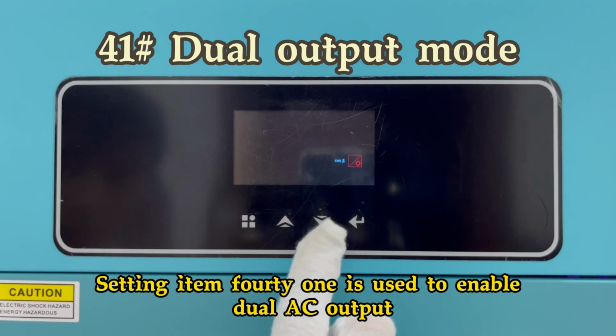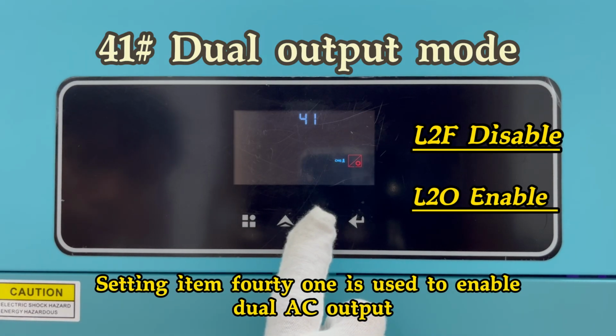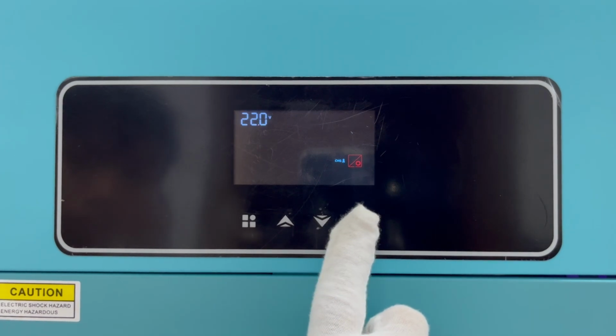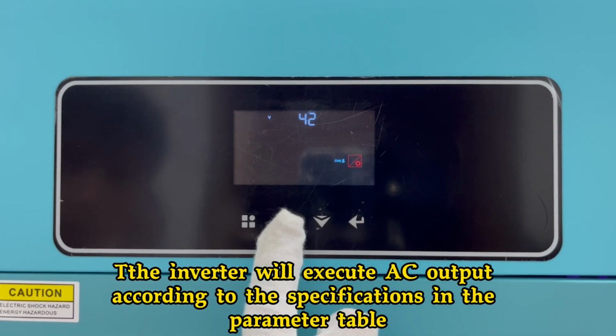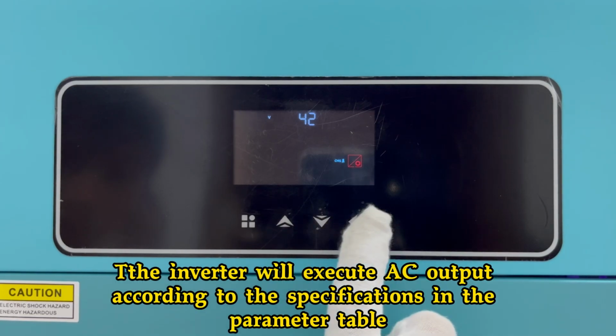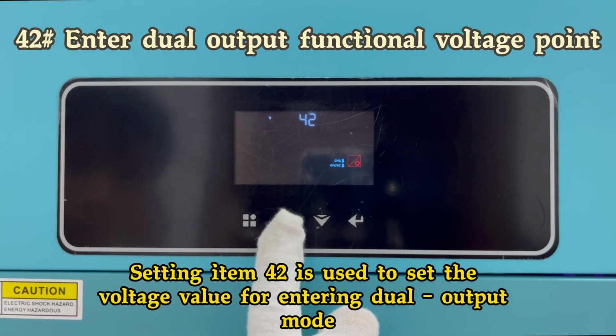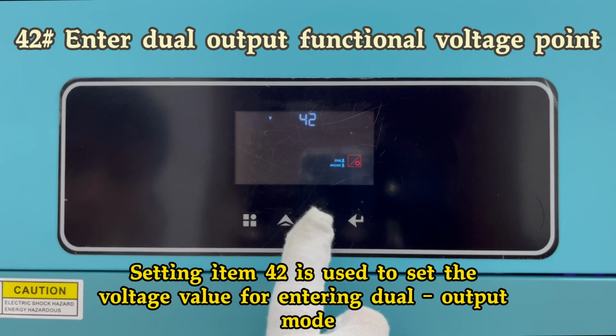Setting item 41 is used to enable dual AC output. It is disabled by default if you choose L2O. The inverter will execute AC output according to the specifications in the parameter table. Setting item 42 is used to set the voltage value for entering dual output mode.